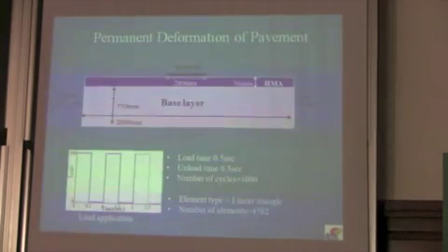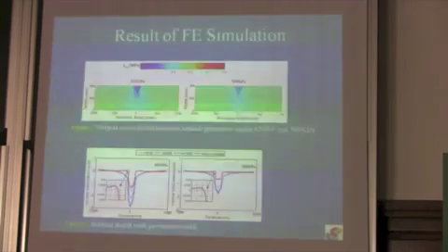Okay. All right. And we can simulate what happens to the pavement as you drive over it. In this case, we have done 1,000 cycles. One cycle takes 1 second, so 1,000 seconds, with this type of loading, right? And these numbers are quite realistic. You have 50 millimeters of asphalt lying over some base layer, and this tire pressure is what a Michelin tire of a certain type applies, and that's exactly what we're doing.